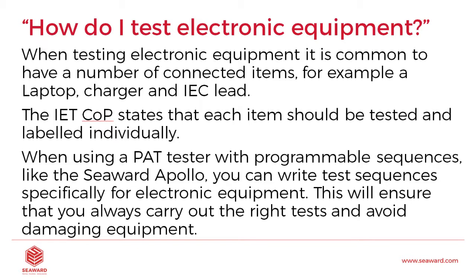When using PAT testers with programmable sequences, like our Apollo series of testers, you can actually write and configure your own test sequences specifically for electronic equipment. Now, this will ensure that you always carry out the right tests and avoid damaging equipment. So again, you can set it up with 250 volt insulation tests, you can set it up with leakage tests, however you feel fit, but they are programmable.